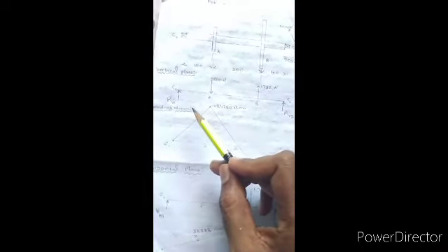Okay. Now you take moment about any one point. Take moment about C1 or take moment about C2. Because at both the extreme ends, particularly on the supports, the bending moment value will be 0. Okay. You take any one point. That is your wish. I am taking point C1.